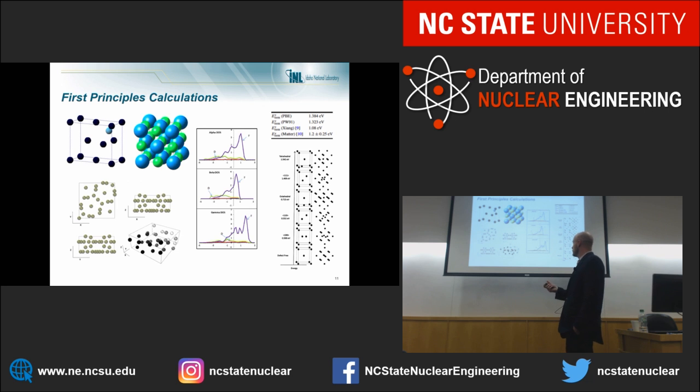We've looked at intermetallic structures of uranium and Zr and uranium and different fission gas species in order to develop interatomic relationships between the uranium and these other elements. We've looked at the density of states of the alpha, beta, and gamma phases to see how the f electrons, which are dominant in the binding of these systems, vary between the different phases.